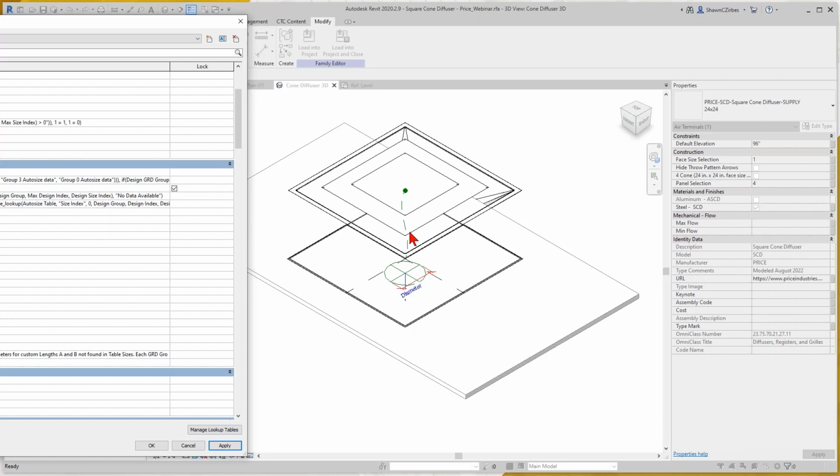That tells me that this particular family, it's originating from the corner of the family and not the center point of the family that's modeled. Most manufacturer content, when I download it, its origin tends to be centroid in the family. Looks like Price specifically modified their family to be corner originating, which is great from a placement point of view, but it's terrible for what I need.